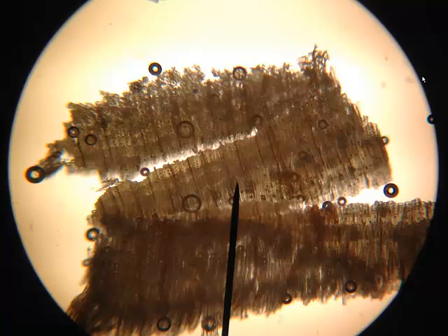We're going to start with a microscope. What we're looking at here under a microscope is a sample of softwood. This is just from standard softwood framing material, but this would be representative of most wood materials. We're looking at a 40 times magnification, and the wood is in a water solution. That's why you see all the water bubbles, or the air bubbles rather, around the image from the microscope.